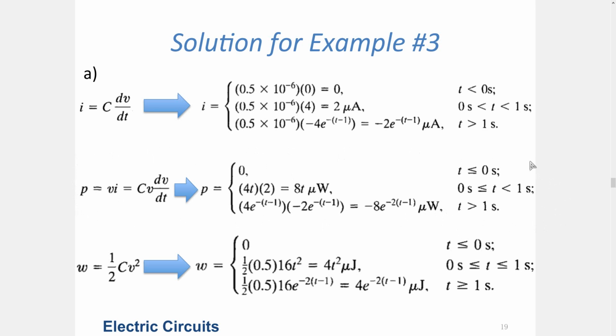Okay, so we have computed the power function for the capacitor. Since we know the power relationship in these three different intervals, we can also compute the energy for these intervals, because energy equals the integral of power over an interval, and we have these intervals. So we can simply take the integral of these expressions that we have found, then put the boundaries and compute the energy and obtain the energy expressions.